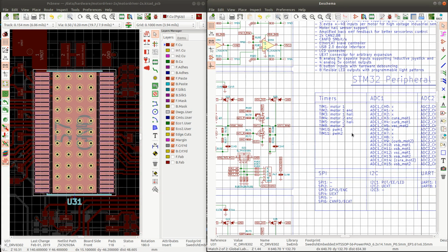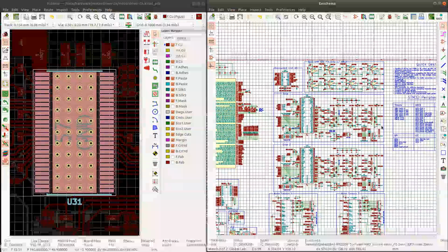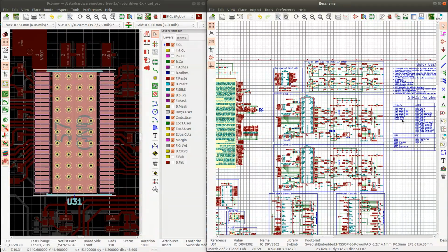The only tricky part here is that there's certain things that need to happen in the motor driver as a response to changes in, for example, the Hall signal, and they have to happen very quickly after the change in Hall signal. Trying to separate this code into multiple drivers will become problematic, I think, considering that it has to be very short response times. It has to be very real-time. Code is designed to run in real time.